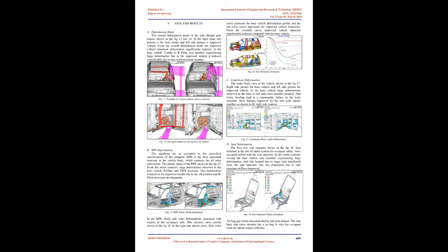As per the baseline study, the important load transfer path members identified are the B-pillar and its reinforcements, roof bows, sill, and transfer cross members. The stiffness of these parts was increased by way of design changes and material grade up. Fig 11 shows the various stiffness-increased parts.